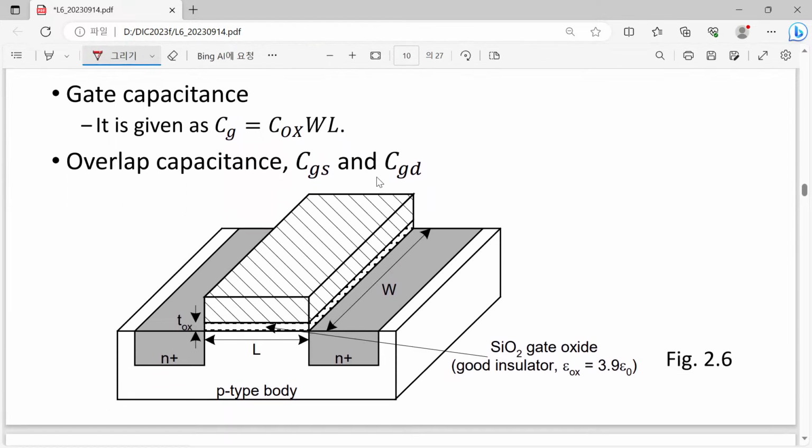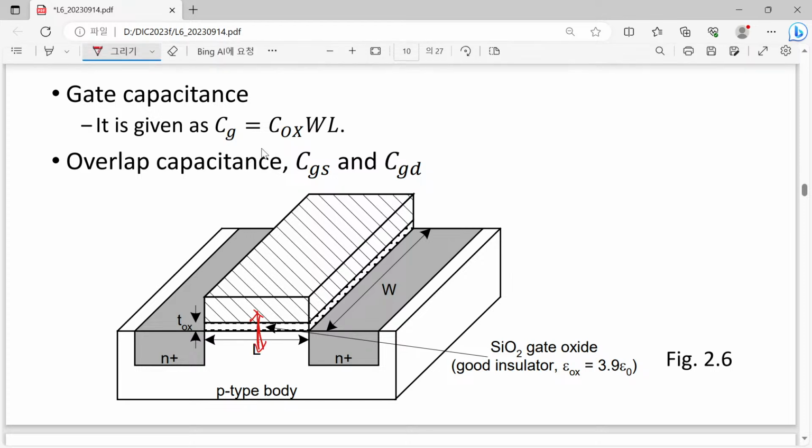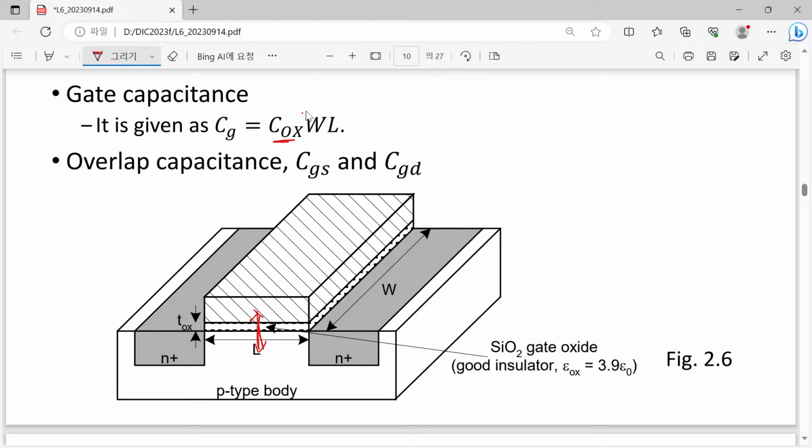So now let's go to our figure, and as I explained up to now, here we have the capacitance, and this is corresponding to Cox. Once again, Cox, although called oxide capacitance, is not exactly capacitance itself. This is capacitance per unit area, and just multiplying by the area, the drawn area of our metal, then we will get the quantity corresponding to farad.